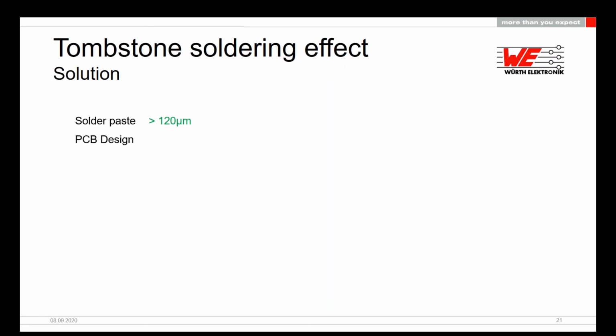The PCB design. Please refer to our recommended land pattern in our datasheet for your PCB design. To avoid the oxidation, please follow our MSL3 handling for SMT LED. By pick and place issue, the components need to be placed centered on the land pattern.